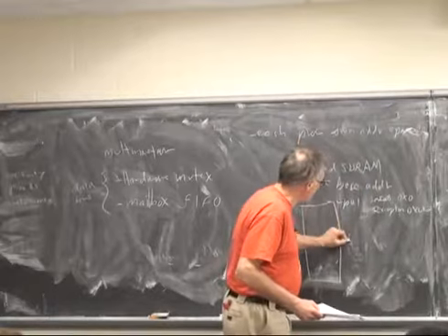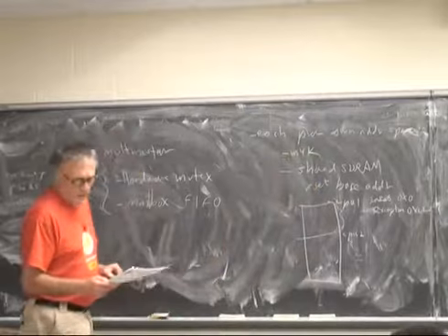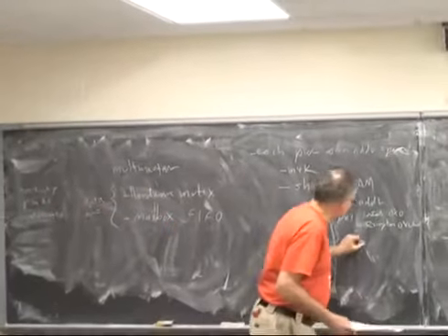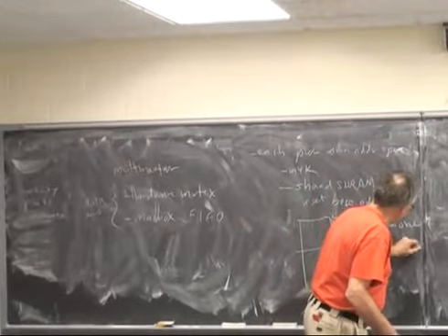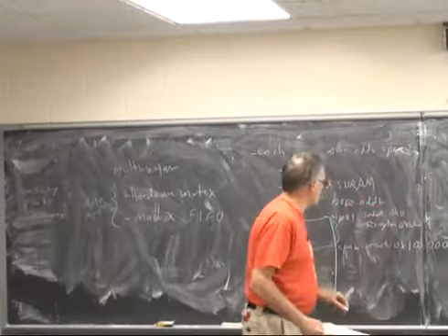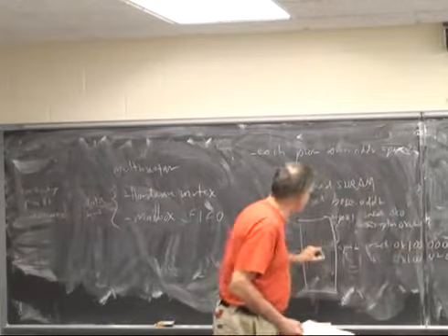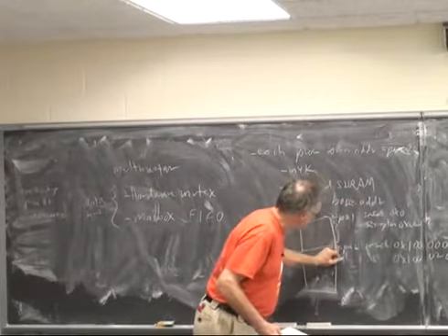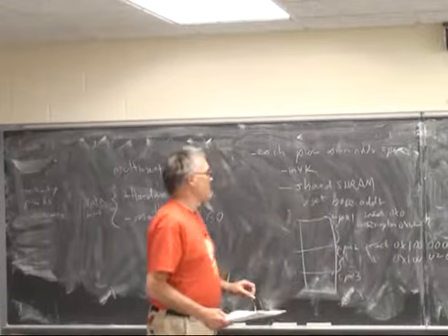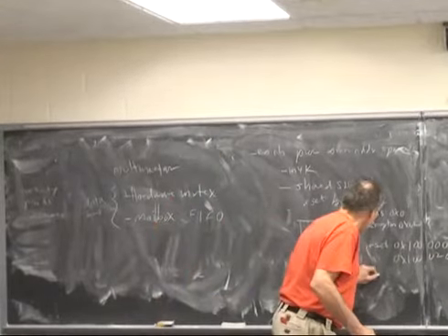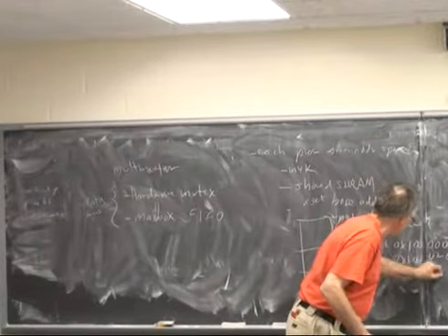And CPU 2, so CPU 1 has all this space. CPU 2 then might start with a reset vector of 0x100000, and an exception of 0x100020, and would have access starting at that address up until CPU 3's reset address, which might be 0x200000.